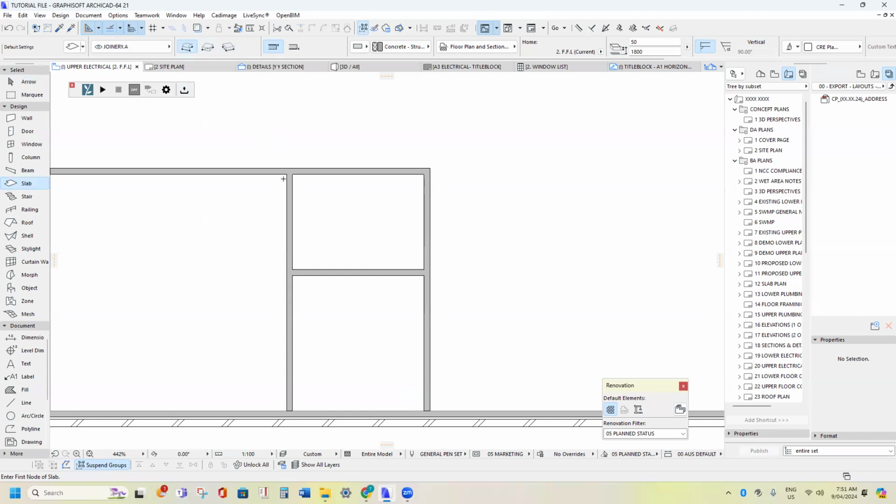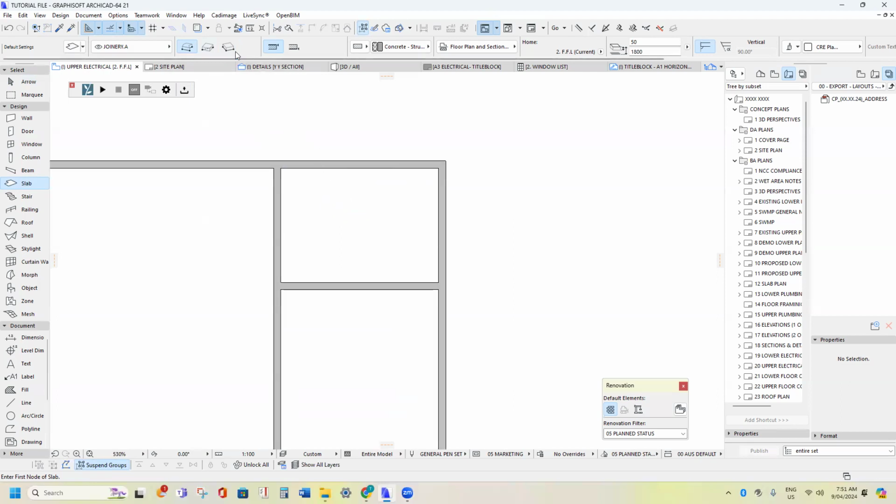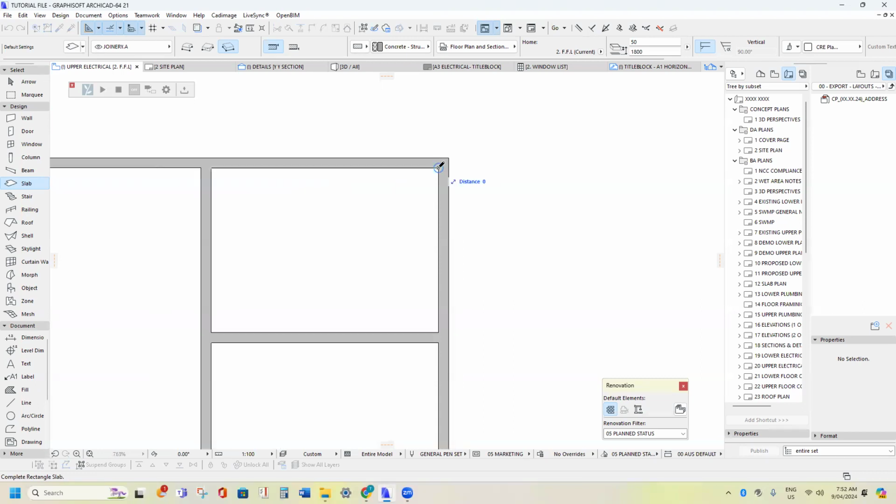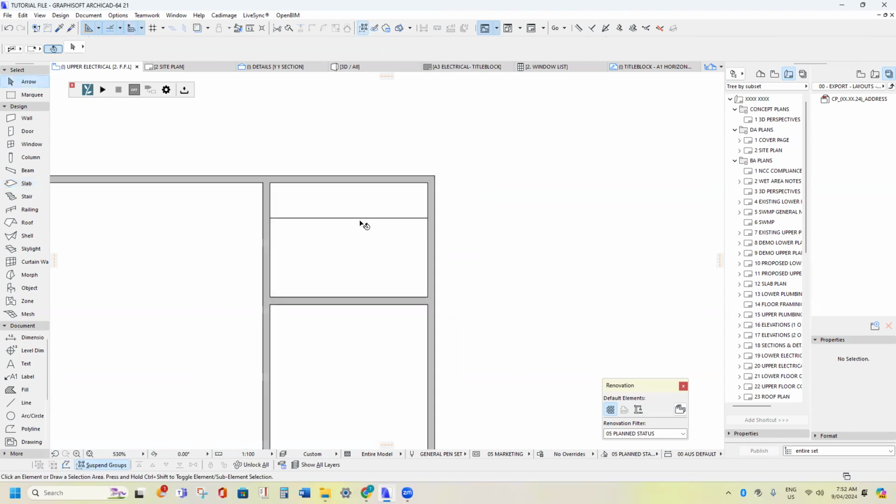You can do multiple clicks, for example, but for this object, it's just a rectangle, so it's quicker to click on this option. And so you click on the corner, click on that corner when that pen goes black. If you need to zoom in to make sure it's connected, do so. And then you come this way and it drags it all out, and then you press R 450. That's your walk-in robe shelf.